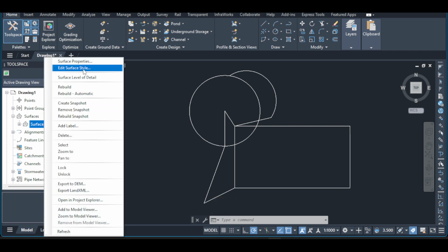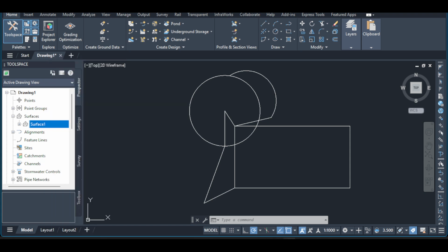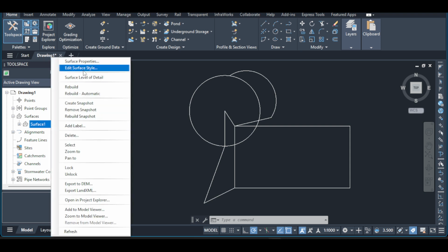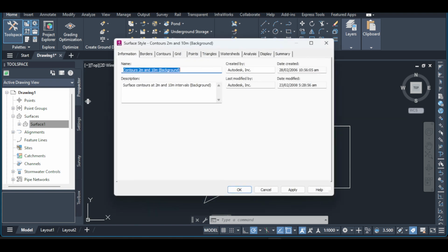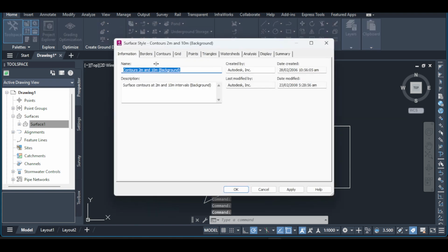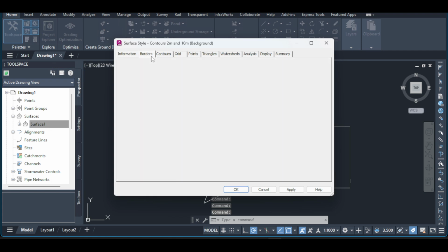Next, decide what kind of trim you need. If you want to clip the surface to a limit, say to match a property line or a project area, choose Add Outer Boundary. This keeps everything inside your closed shape and hides everything outside. If you need to remove an unwanted hole or gap inside the surface, choose Delete Inner Boundary. That option clears an interior boundary so the surface fills back in where it was previously hidden.